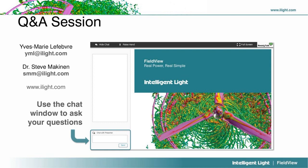If you were to save the full results over time, some customers do this, you could also run FieldView in batch. Each time a time step is saved, you could process it, generate the extract in batch, and work from the extract. So there are several options before a full in situ instrumentation that are possible. And I'm sure I mentioned it, but the export from OpenFOAM will typically be in VTK format, and of course there's a VTK reader in FieldView.